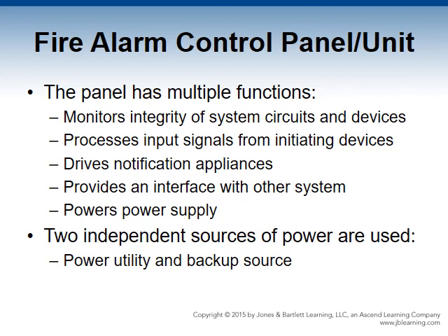They should have 2 independent sources of power. The main source is usually powered by a utility. The old systems used 120 volt alternating current, or VAC. The modern panels convert voltage to 24 volt direct current, or DC, through the power supply circuitry.